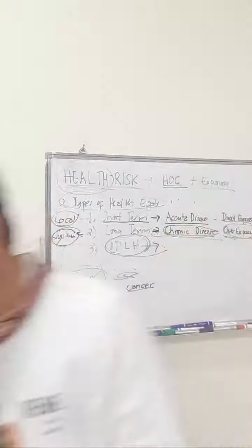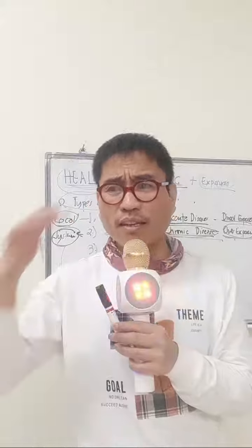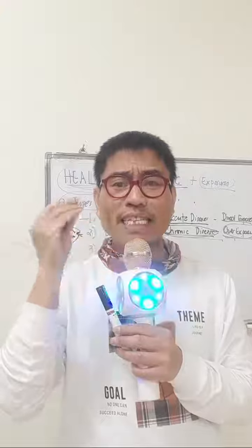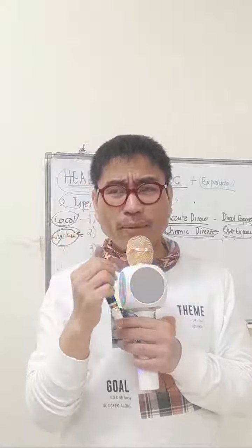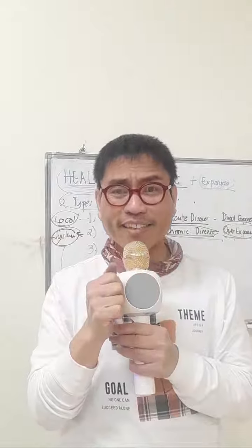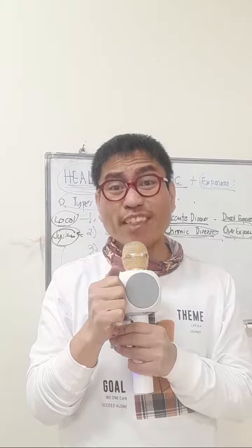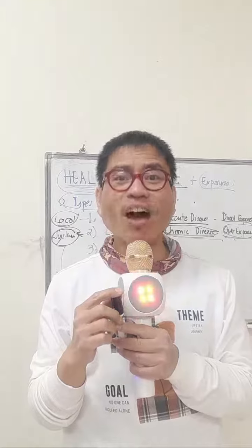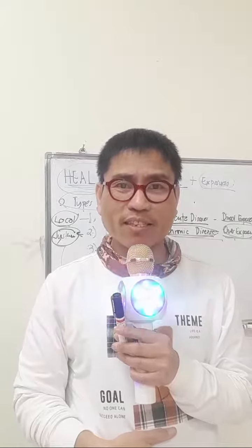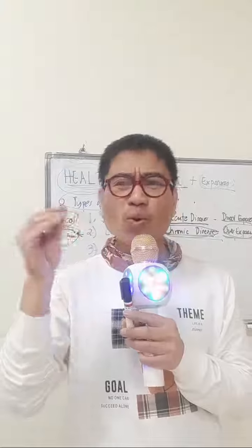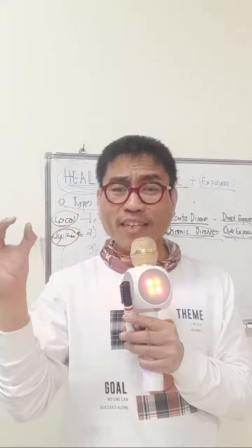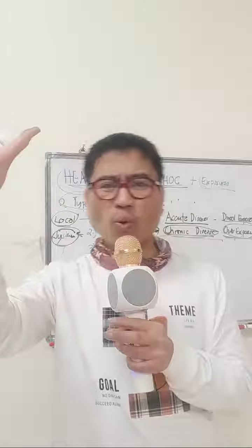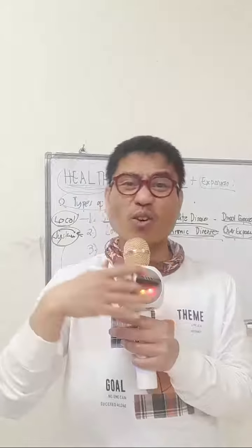Threshold limit value, what is the definition for this? It is the allowable concentration level of the contaminant vapor or contaminant toxic vapor to which a human being can be safely exposed for a maximum of 8 hours without adverse health effects. Meaning there's no abnormal effect even though you are exposed for 8 hours.